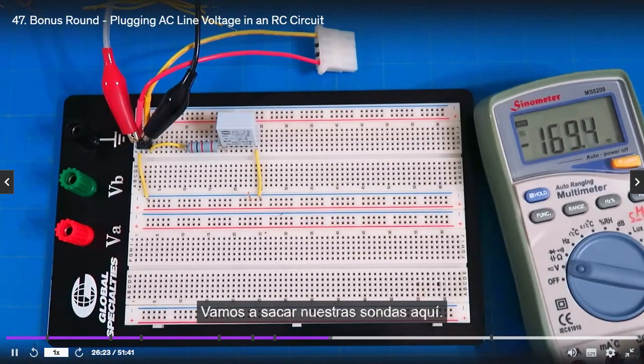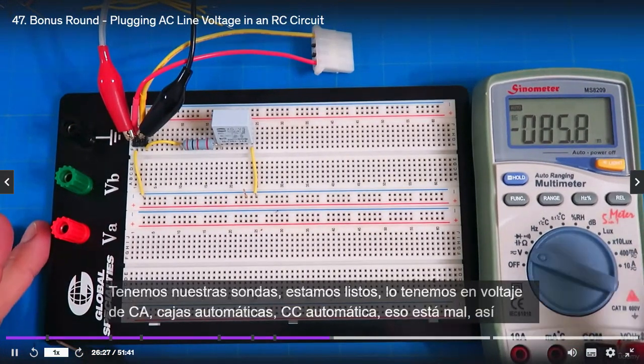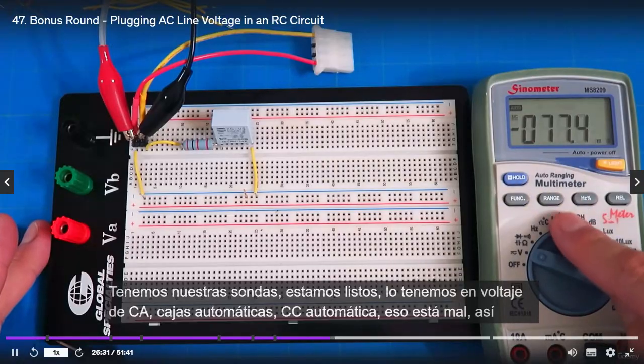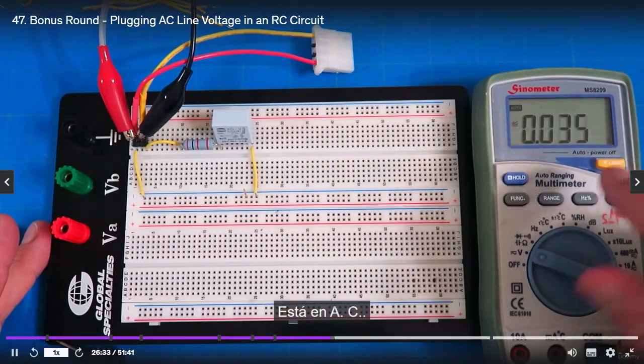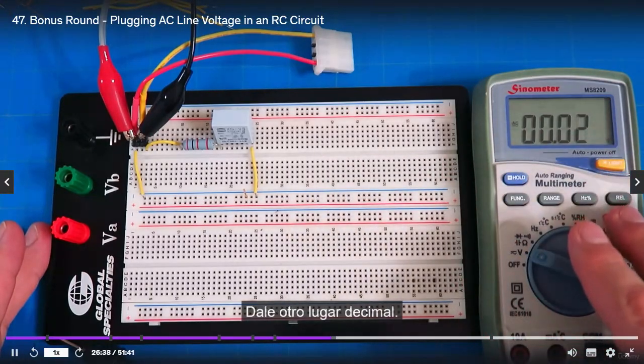Let's get our probes out here. All right, got our probes, we're good to go. We got it on AC voltage, auto. Okay, it says auto DC, that's wrong. So let's go to function. It's on AC. Is that better? And let's put the range, let's give it another decimal place.